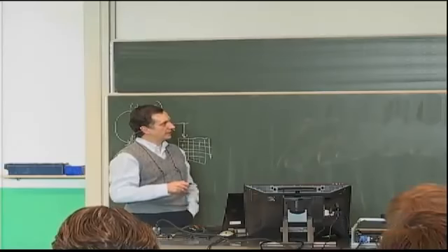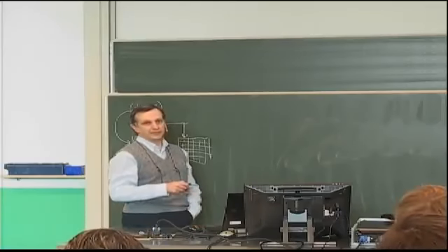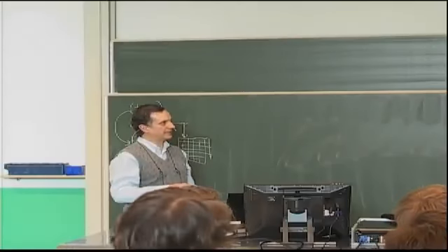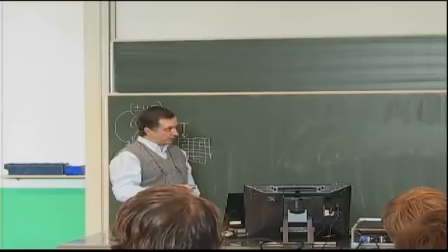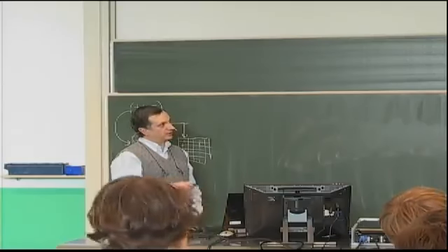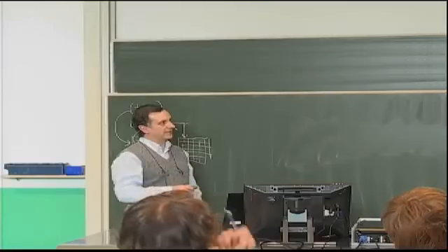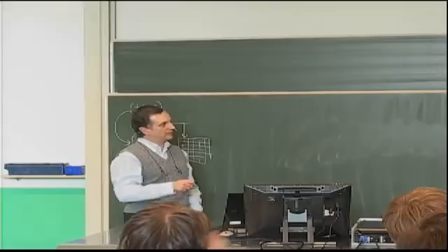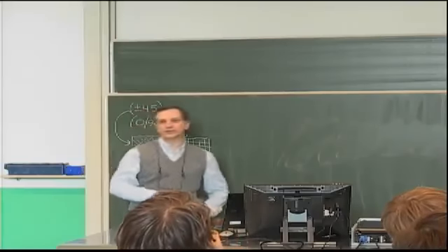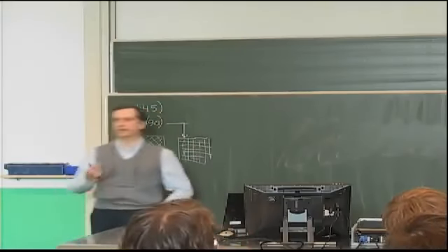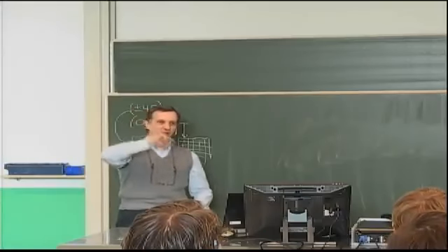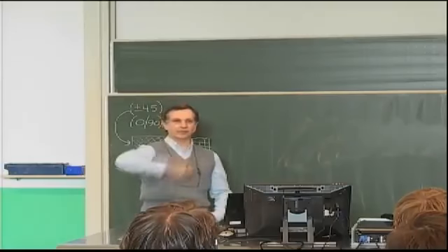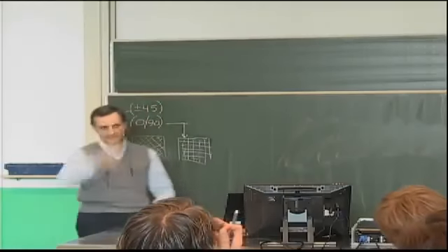So if I satisfy equilibrium equations approximately, that means I'm doing a displacement-based solution and I satisfy exactly my strain compatibility. I definitely need to impose the boundary conditions on displacements to be satisfied exactly. Minimizing the energy will do two things. It will satisfy approximately my equilibrium equations and will satisfy my force boundary conditions in an average sense. That is, point by point, you might not get a force being zero at some location, but if you were to integrate at that location through the thickness, you would find that that integral is zero.